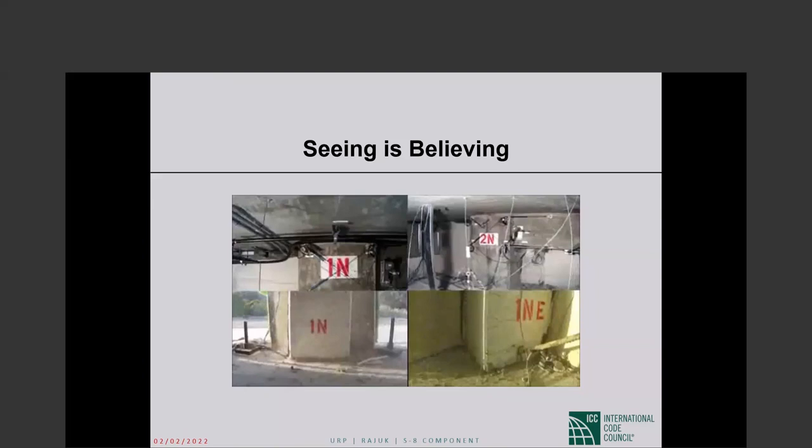So the next question is: to calculate seismic dead load, 100% of dead load and 100% of permanent heavy equipment load is considered. However, for live load, seismic dead load is 25% to 50% of live load. Can you explain this? I don't even understand the term seismic dead load, seismic live load. Dead load is dead load, live load is live load, seismic forces are seismic forces. There is no such thing as seismic dead load.